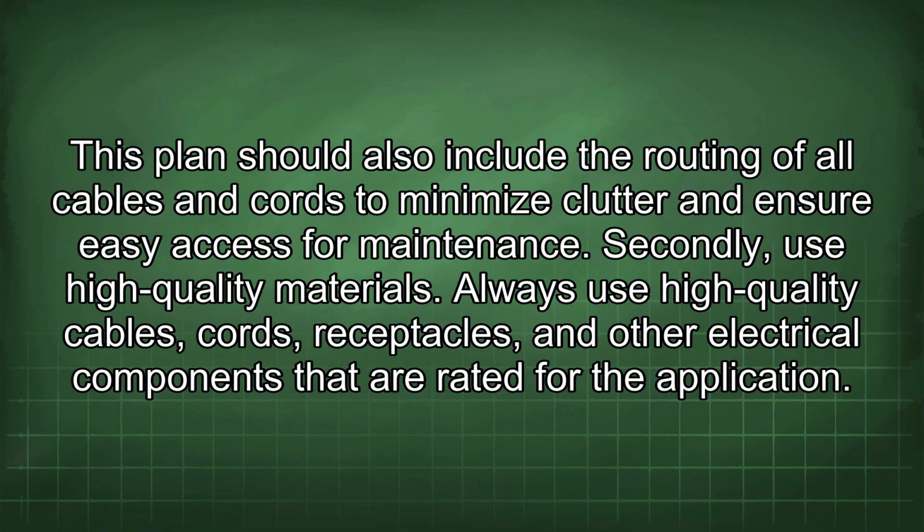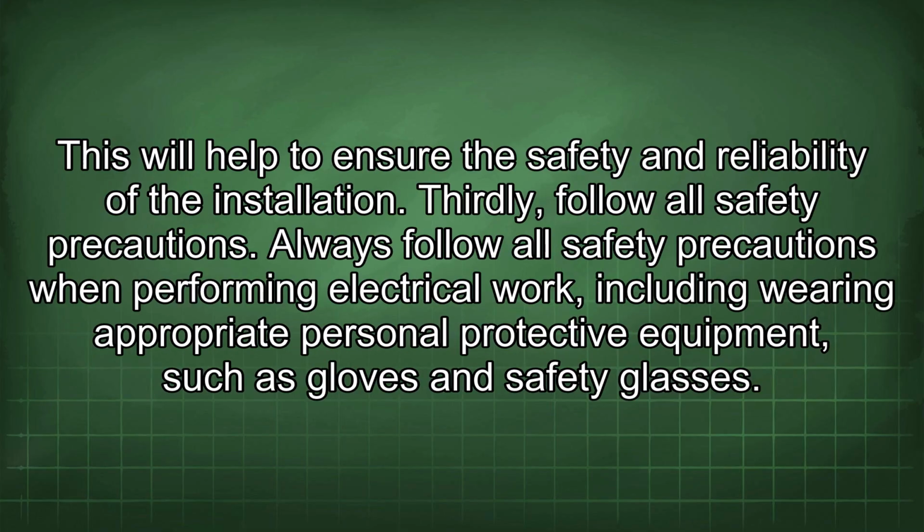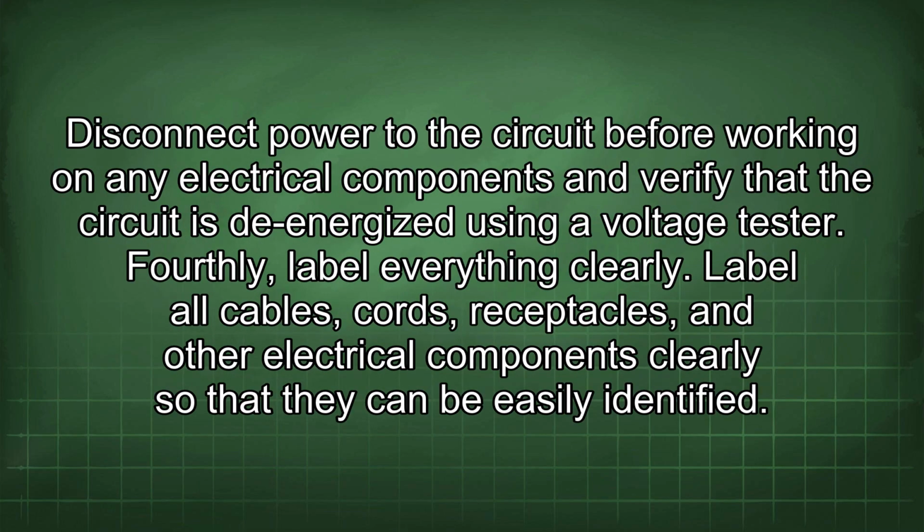Secondly, use high-quality materials. Always use high-quality cables, cords, receptacles, and other electrical components that are rated for the application. This will help to ensure the safety and reliability of the installation. Thirdly, follow all safety precautions. Always follow all safety precautions when performing electrical work, including wearing appropriate personal protective equipment, such as gloves and safety glasses. Disconnect power to the circuit before working on any electrical components and verify that the circuit is de-energized using a voltage tester.